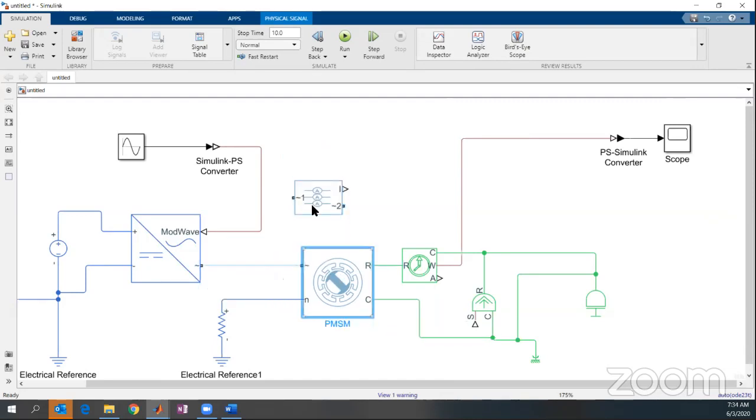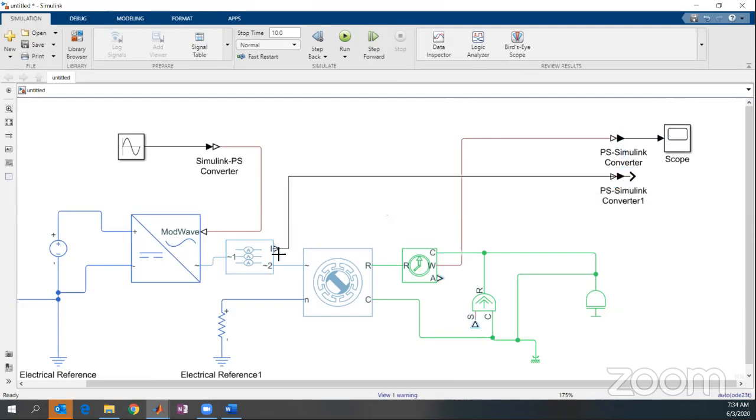It's very intuitive, as you know, in the physical world, especially when we are running the experiment, all we know is the current sensor is always in series with our circuit, right? So it's very intuitive. You just connect this current sensor in series, and then we can also quickly see the dynamic response of our current sensor just by connecting to this oscilloscope.